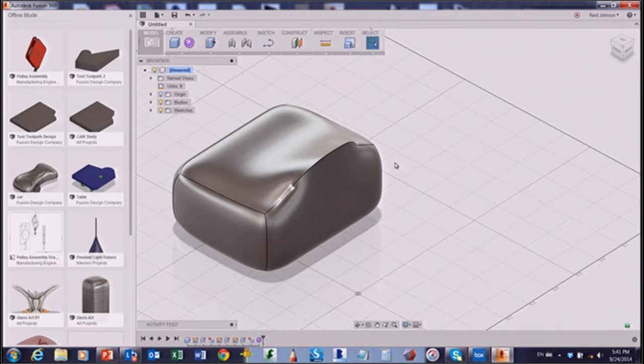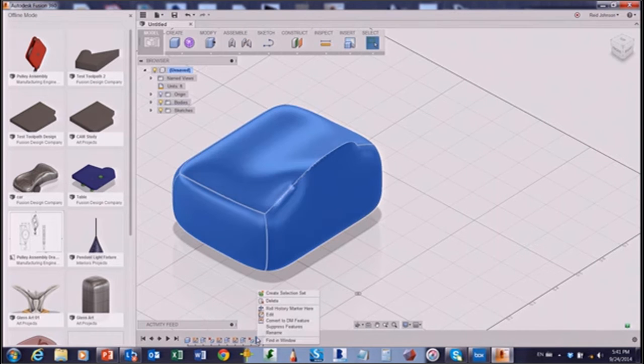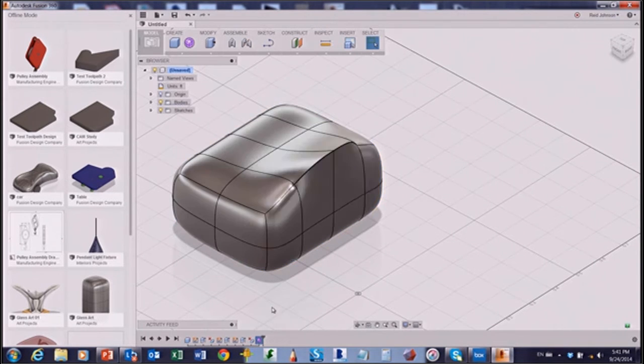When you finish the form, it takes it to what's called a solid body. You can no longer edit this thing. It is what it is. If you want to edit it, you have to go back to Edit Form again. So you find on the timeline your little purple sphere. You can right-click, and you can say Edit. Now I can go back and edit that again. So that timeline comes in really handy. Finish Form.